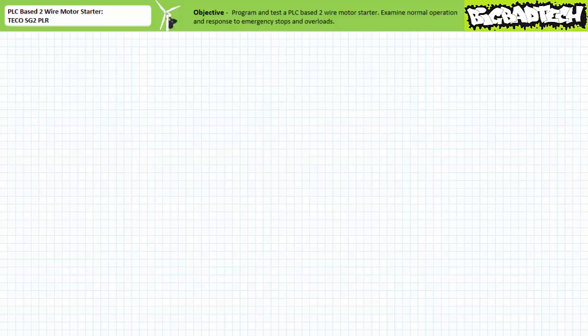Finally, we included an additional rung on our two-wire control circuit that indicates when the PLC is asserting an output, however, fails to receive confirmation. This indicator demonstrated that there is a transitory period of contradiction accounting for the real-world response time of an electromechanical system and is only continually asserted when some outside event, like an overload, is overriding the PLC program.